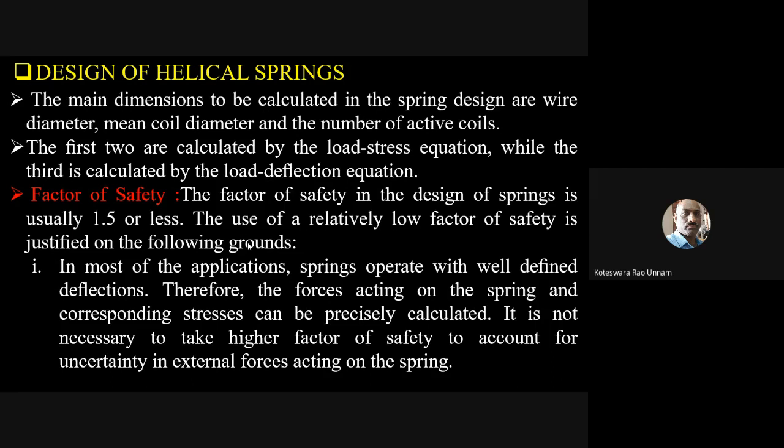The factor of safety in the design of spring is usually 1.5 or even less than 1.5. The use of relatively low factor of safety is justified on the following grounds. Why we are using very less factor of safety in case of spring design is because in most of the applications the springs are operated with well-defined deflections.